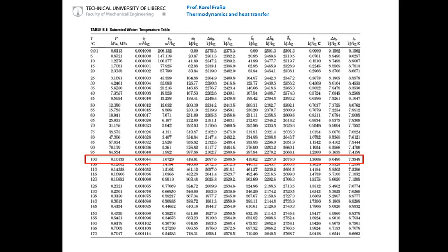In the second table, there will be only one value for the specific volume, the internal energy, the entropy. However, if you use the saturated mixture, you still have to use two values for the saturated gas and saturated liquid. So if your calculation requires these two values, you will automatically know that you are in the area of the saturated mixture.